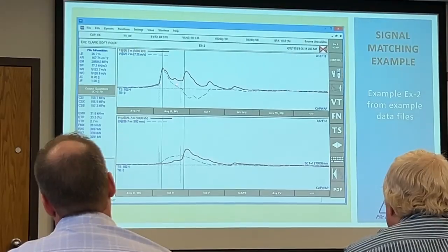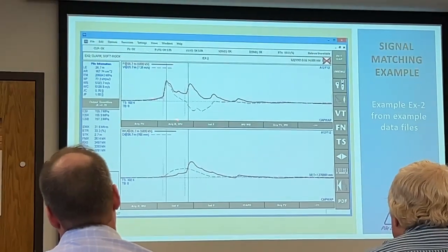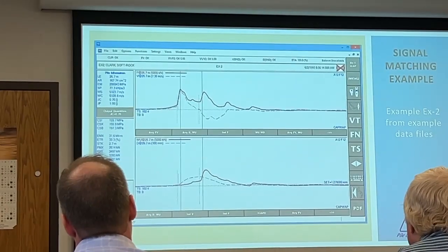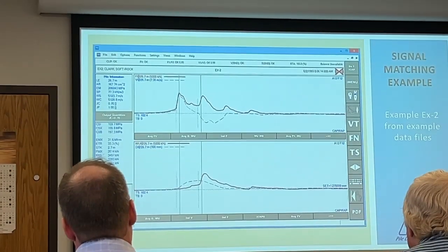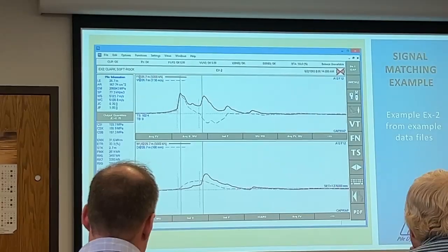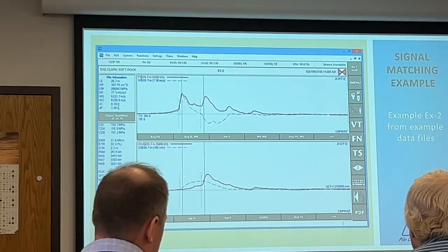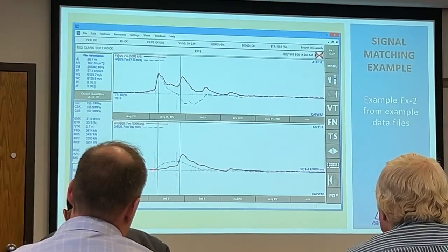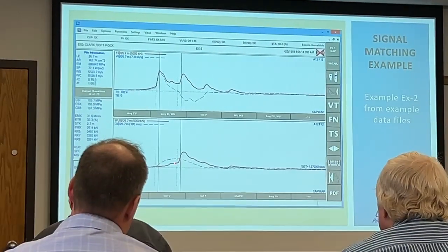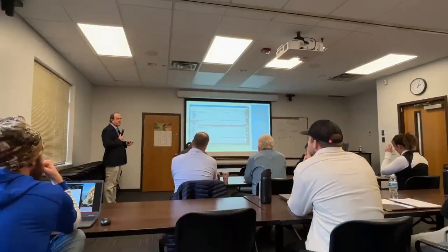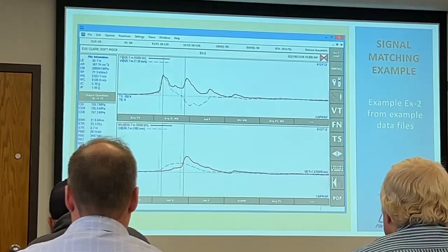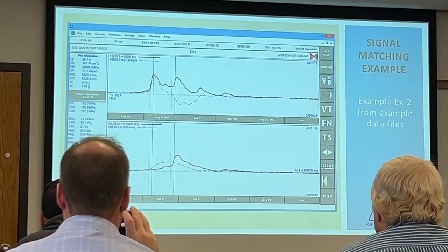Velocity is trending towards 0. Force is rising. Fixed. If the velocity is trending towards 0, then it's a fixed end. Is it going back to 0 at the end? Yes. The wave up is showing gradually increasing compression followed by a sharp compressive response, which is again corresponding to a fair bit of shaft resistance and a fixed end condition.